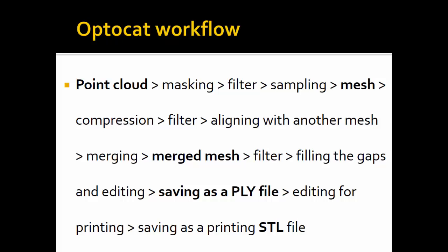I have to align my meshes with each other. So say if I have 800 point clouds, I also need to align all the point clouds and all the meshes together. And then I merge them into a single surface, thus, first of all, removing all the redundant data, and then potentially choosing between different overlapping meshes, choosing the good points, the good triangles, the more reliable ones. For example, calculated based on an angle between the scanner and the surface that it captured.